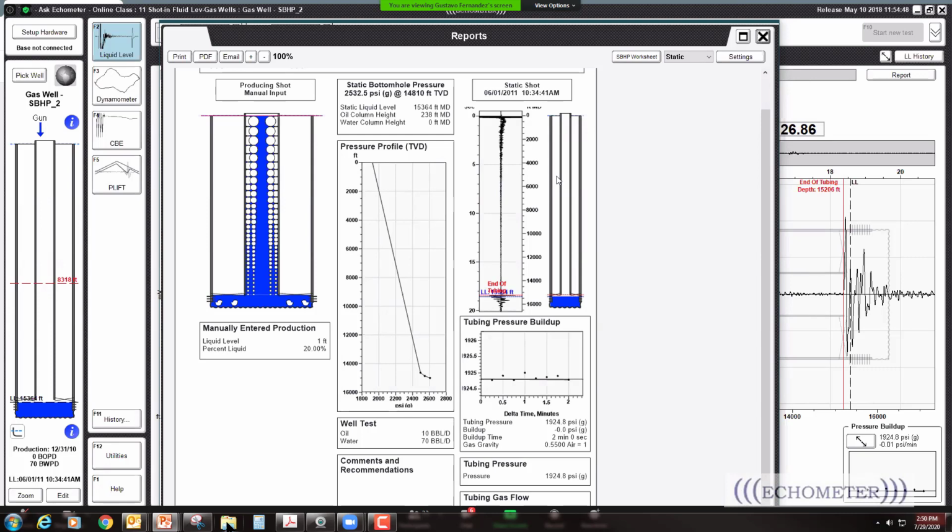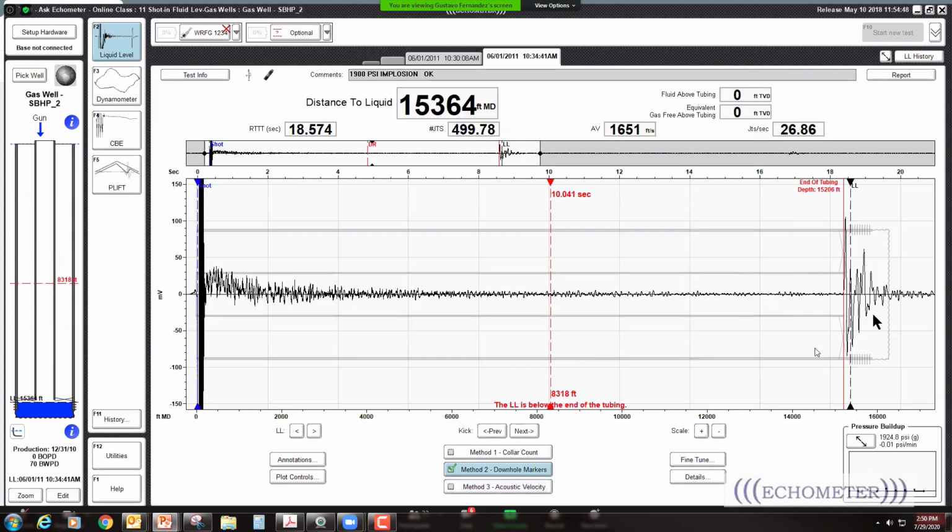And in this case, for the high gas pressure and rate, the liquid level is pushed down back to the formation on the static condition. That's the three examples that you might be facing. It's really common to see empty wells or no liquid columns in a gas well. And I'm ready if you have any question.